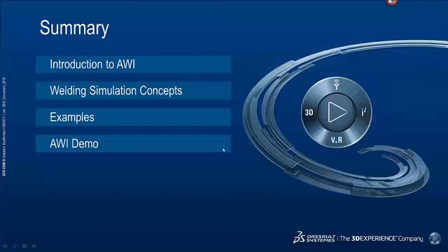So just to summarize, we talked about welding simulations and how the Abaqus Welding Interface had been such a successful plugin to model welding. And the first customers actually started using that for additive manufacturing simulations. We saw how that triggered multiple solver and subroutine enhancements, both in R&D and the field, to efficiently model the AM process. And now we have come a full circle, using these enhancements for AM for our new generation AWI that we call AWI Pro.